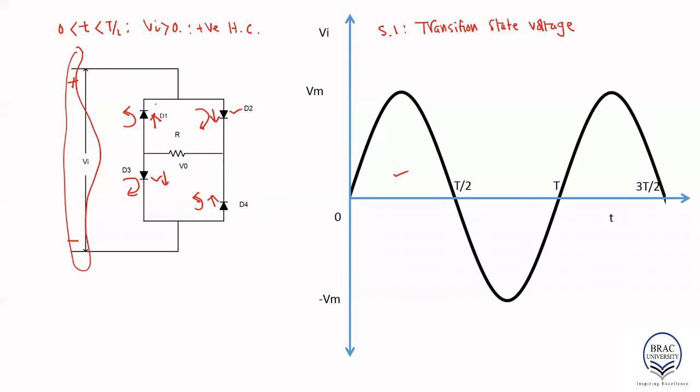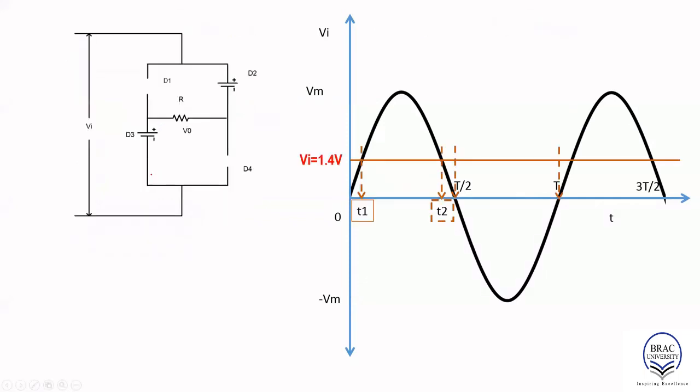So in that, we notice D1 and D4 appear to be reverse biased with reference to this signal, because the N side and the positive terminal are on the same side, and the P side and the negative terminal are on the same side. However, D2 and D3 appear to be forward biased. So that means we can reduce the number of diodes. So D1 and D4 are gone.